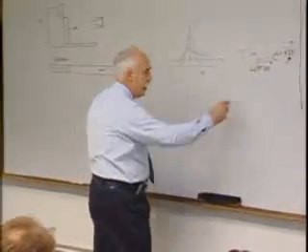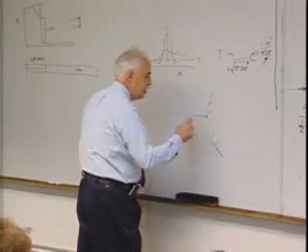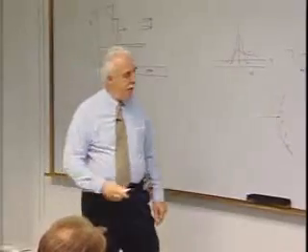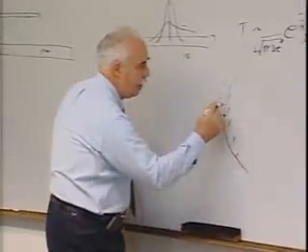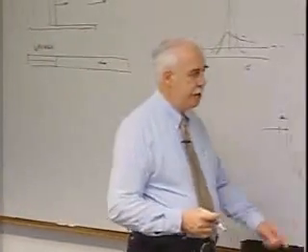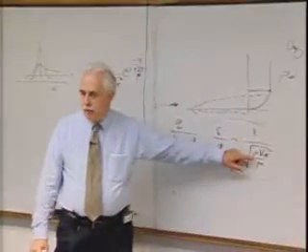If you look at the stagnation point on a sphere, this is a singularity. You go to spherical coordinates, you've got basically the same phenomena. The diffusion from the wall gives you characteristic dimensions. Very important because heat transfer is basically inversely proportional to the square root of Reynolds number.